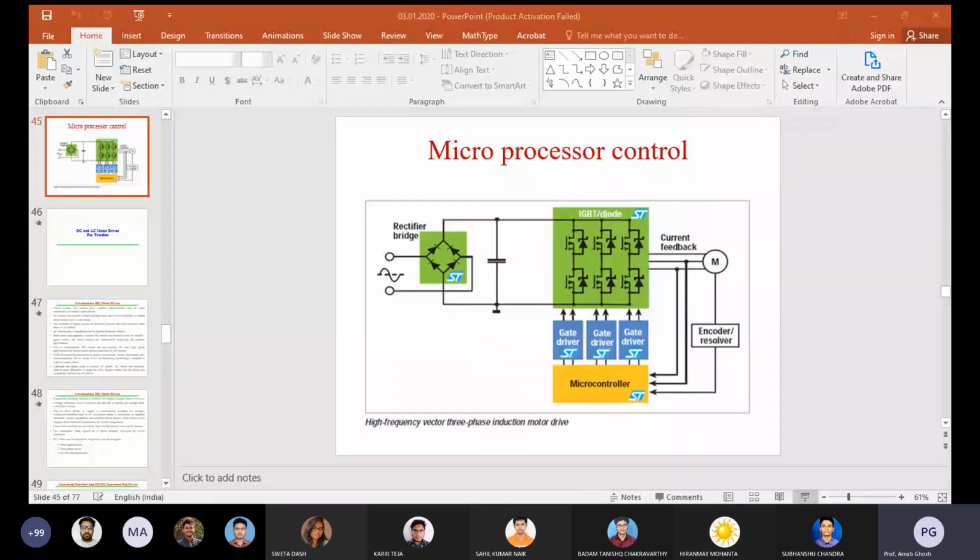So AC you are giving, then it will be rectified to DC through the direct bridge rectifier or the controlled rectifier, and then you are getting the variable field voltage. A variable value of DC means VF will also be different, so you get a different value of field current, and based on it you are controlling the speed of the motor. So I think you are able to understand the drives.